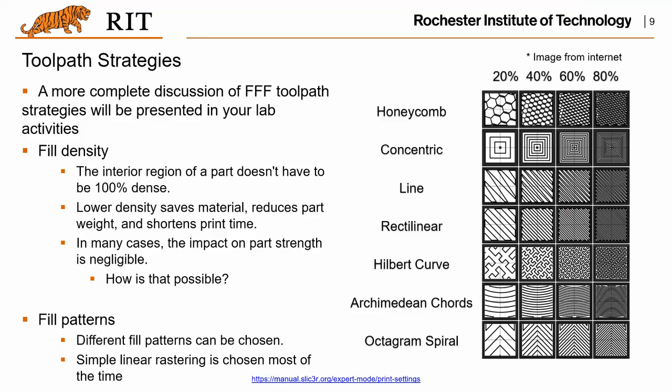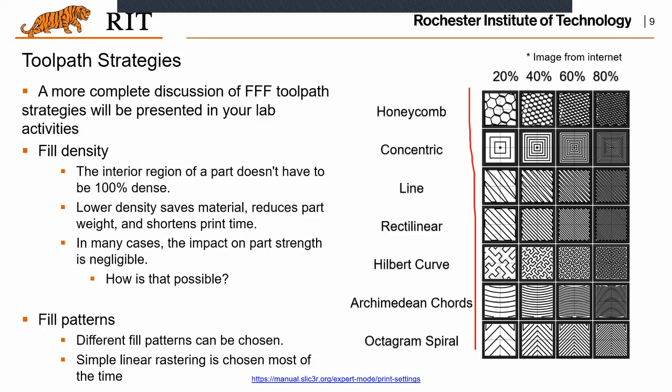So there is another setup you want to play with in fused deposition modeling printing. That is the toolpath. A part to be printed using fused deposition modeling is not a whole solid part. Actually, there are some hollowed regions, and you need to look at how you want this hollowed region to look. And that's the infill. So in each layer, instead of printing a whole solid layer, you could print these patterns. There are different patterns for you to choose.